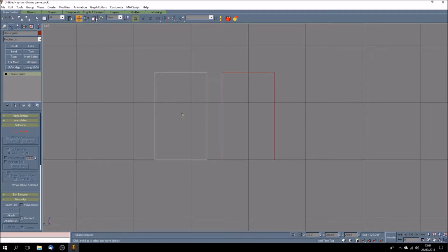select and uniform scale, that where it shows it with the same proportion of square inside a bigger square, it means it's going to shrink it down in proportion. But if we want to change that and shrink it down in a different way, we can choose this option, which will shrink it down in only one direction, and the direction is determined by which coordinate system you use.